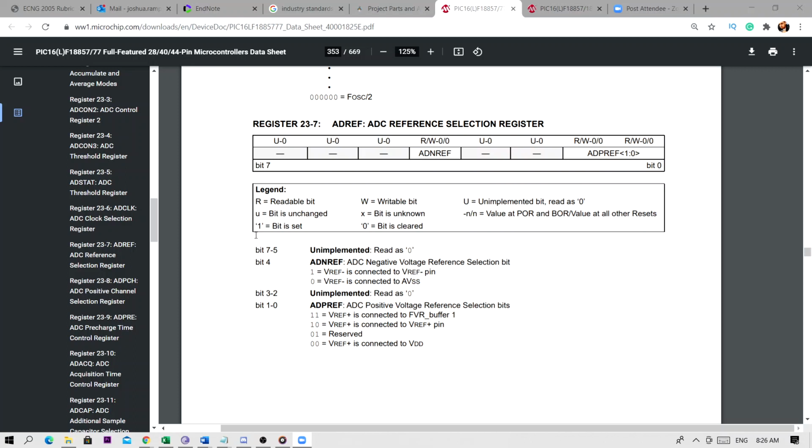I can't get volts out of this thing, right? But what I'll get is a number representing not the 2 volts, but where 2 volts is on the scale, right? So what I'll get is a number that looks like 2 to the n times my 2 volts, subtract 1. In other words, the voltage difference between my voltage and my negative reference, yeah?